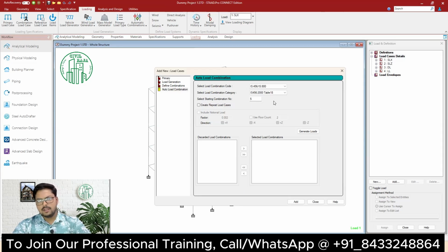That is not an issue. But even if you are doing it over here, that is fine. So since we are not using the RCDC right now, I will go for the generation of the load combination. And I have already shown you that our column is passing at 4 bars of 12 mm dia. Now we will see what will happen after the load combination.